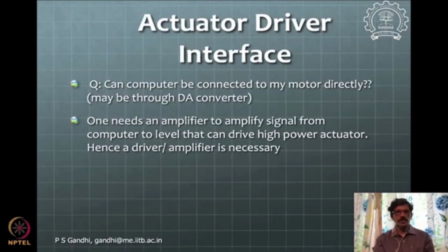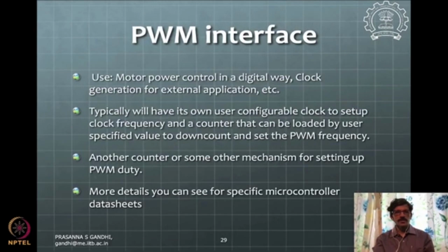So this pulse width modulation is where you have a pulse coming on the pin at some frequency, say maybe about a kilohertz or 4 kilohertz, and a clock pulse will typically have 50% duty, meaning 50% on time and 50% off time.